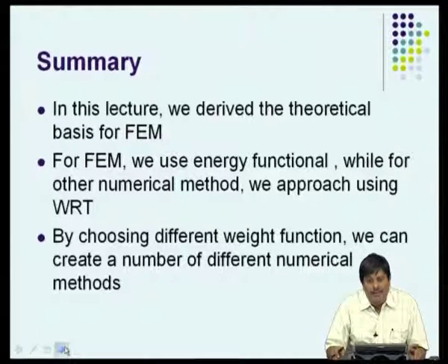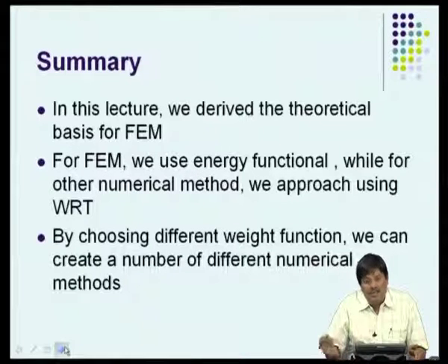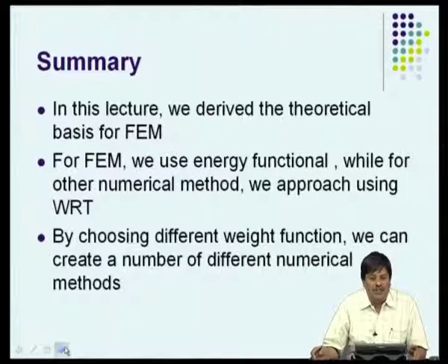In the FEM, we write the weak form of the equation. The weak form can be constructed by taking the governing equation, weighting it with the assumed solution, and integrating over the domain. And while doing that, when we say that the dependent variable is equal to the weight function, we get the energy functional or the weak form of the equation. So, the minimization of the energy functional is the same as obtaining the weak form of the governing equation through the weighted residual method.